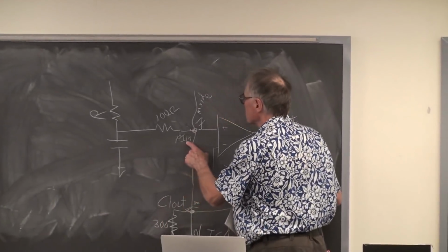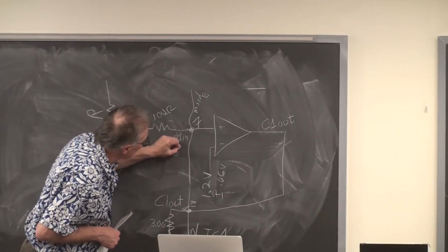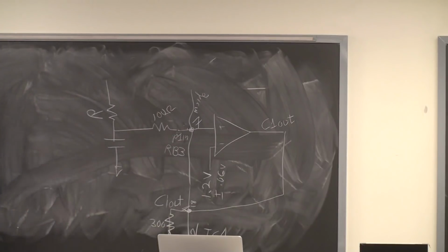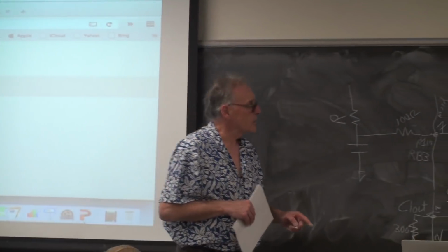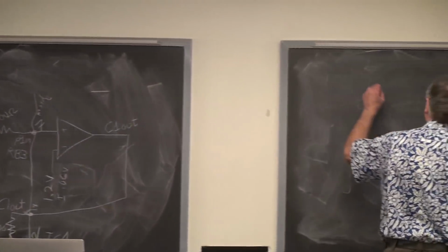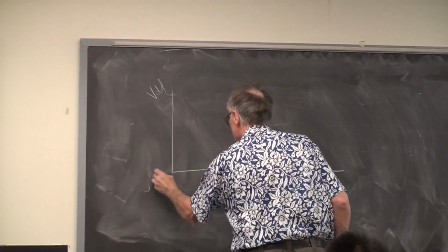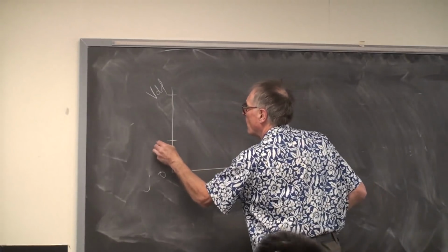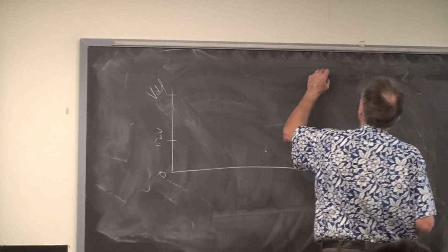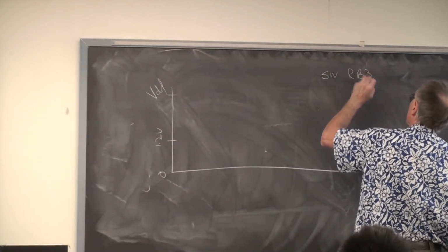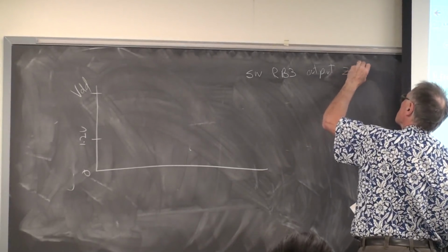So the internal signal is called P1 in, and that is mapped to pin RB3, which is also bit 3 of IO port B. So what we're going to do, if this is VDD, and this is 0, and this is about 1.2 volt here, then we are going to switch RB3 to an output and set its value to 0. Output a logical 0, 0 volts.